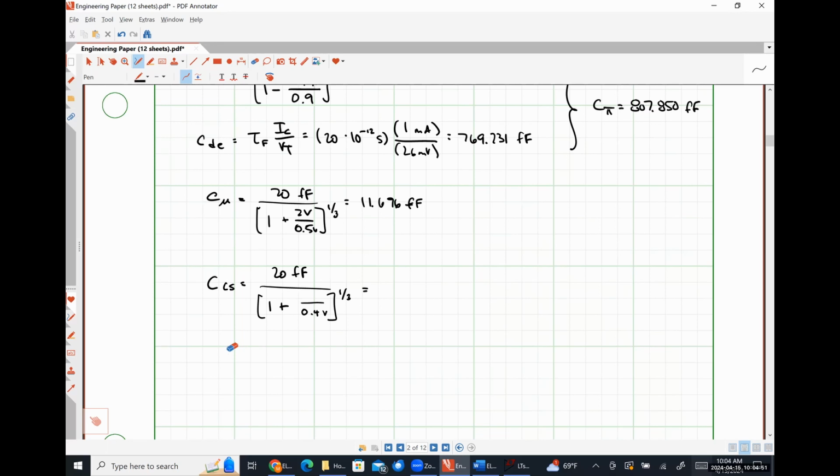Our substrate is at ground, an absolute ground for an integrated circuit. So what would the collector voltage be? It should be the highest point of electric potential in our circuit. So I would argue that it's going to be 2.775 volts. It's going to be the voltage drop across the collector base junction plus the voltage drop across the base emitter junction to give us the total voltage, that very highest point.